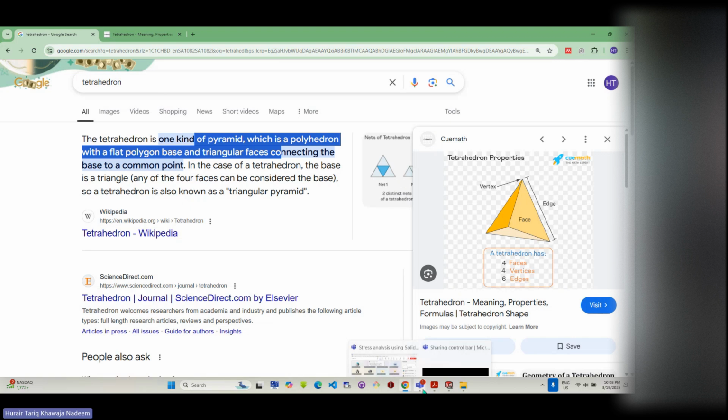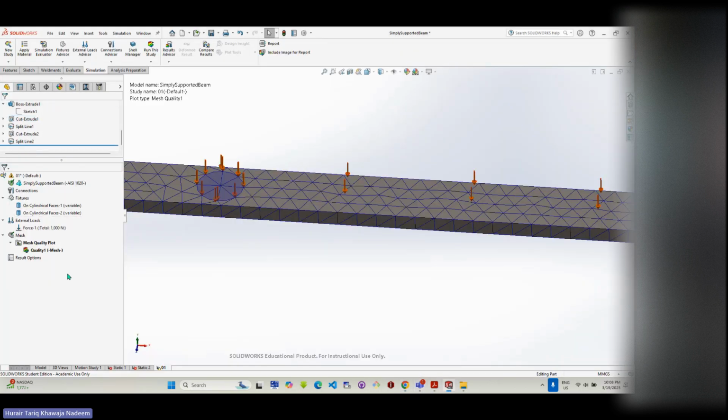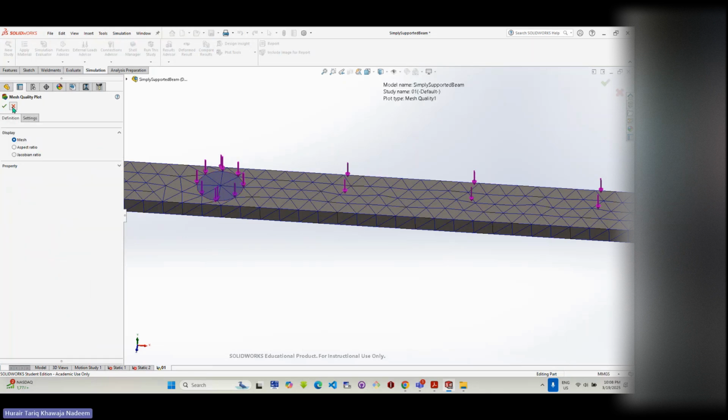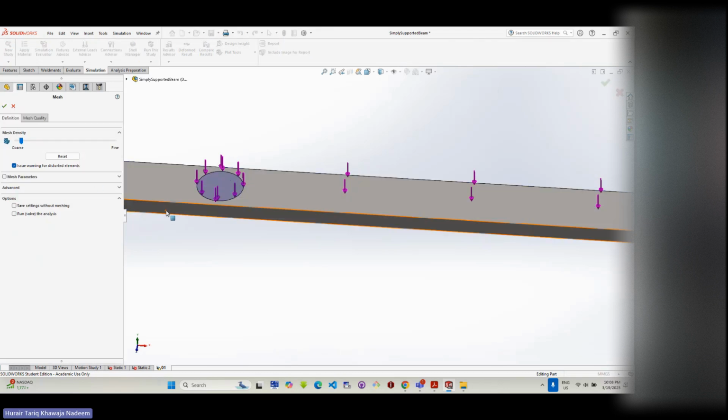But there is something given over here, and it says, if I come to this side, okay, so edit definition, not this one, create mesh. So if I come to this side, this is draft one. Now the high quality has a curved edge. You can see it's curved, and they have got extra nodes in the middle as well. Okay, so this one is going to have 1, 2, 3, 4 plus the nodes in the middle. So 1, 2, 3, 4, 5, 6 extra nodes.